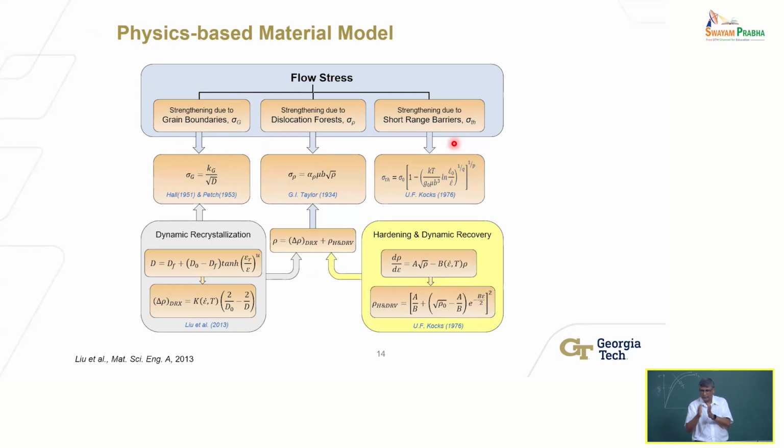You have to get past those type of forces as well. And people have come up with equations to describe these things, okay? These are equations to describe essentially how this grain boundary is strengthening. This may be the most familiar to you, for some of you anyway, the Hall-Petch relationship, which says that the smaller the grain size, the greater the strength of the material, right?